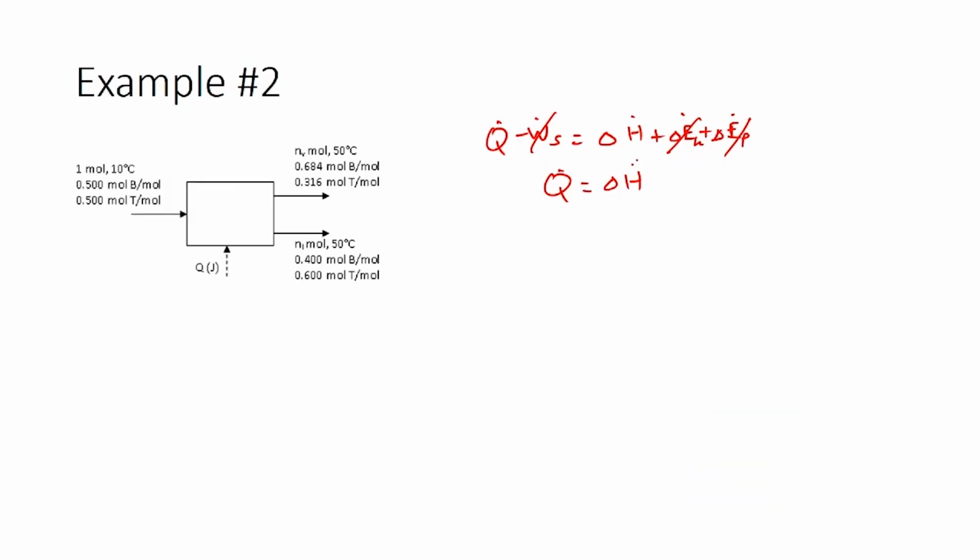Now we need to build the enthalpy table. For building the enthalpy table, we need to have the reference states for benzene and toluene. We will have to prepare the reference states for benzene and toluene and also account for the phases of these, which means we would actually have 4 distinct components when we build the enthalpy table. We would have benzene liquid, benzene vapor, toluene liquid and toluene vapor, and we need to make sure all are listed separately. However, when we choose the reference state, we will choose one reference state for each chemical component separately. So, we will have one reference state for benzene and one reference state for toluene.